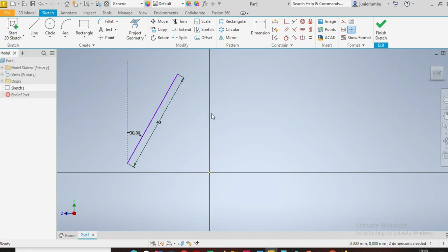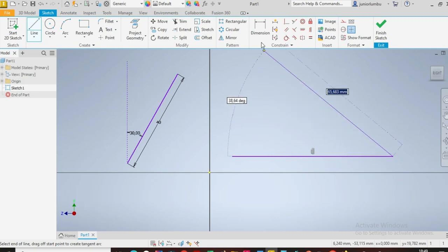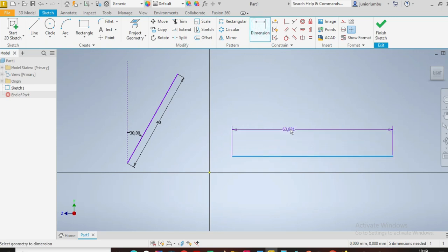The same way, instead of using the input tool that was there, you can just create the line as you want. If you want to go straight, as you can see, it's locked in already, then you go straight. You can see it's telling you that it's right there with 90 degrees. Once you click on the point, you click how long you want it to be. However, if you want to change the dimension of this length, then you come to dimension there, click on it, then you give the dimension by saying, for example, 65 millimeters.